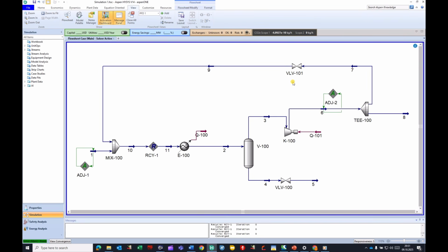In addition, we have anti-surge valve sizing and also settle out calculation for blowdown, cold blowdown, and also settle out calculation for emergency depressurization. So the compression loop is a really classic system in process engineering.